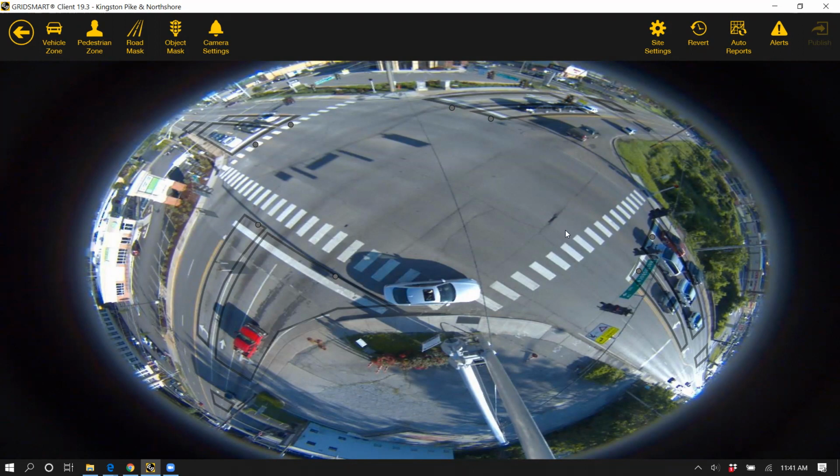Jamie Short asks, will the right turn lane cause a running red light trigger in the data if showing the phase? Yeah, absolutely. Exits on a red could trigger, which is an important reason why you can have your lane by lane detection, because if it's just a right-hand turn pocket and it's triggering exits on a red, well, you know it's a right-hand turn. Sometimes that matters. Some intersections are posted no right-hand turn on red. So again, then you can still track that movement, right?